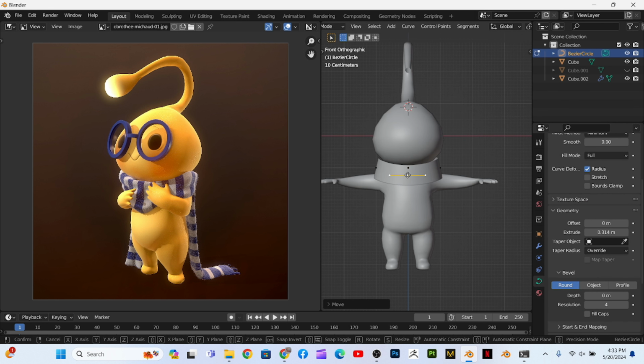For this add a 2 level subdivided cube, make it shaped like a reference, join it with the head mesh, select the both edges and add a bridge edge loop. And do some size adjustment. Now our body and face blockout is ready. Next we will do the face detailing like eyes, glasses and mouth part.